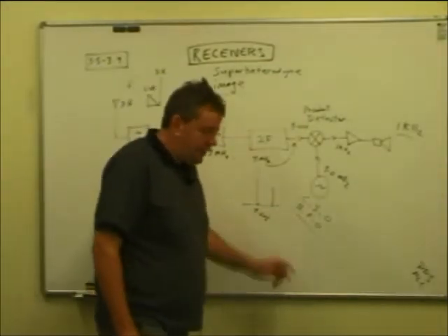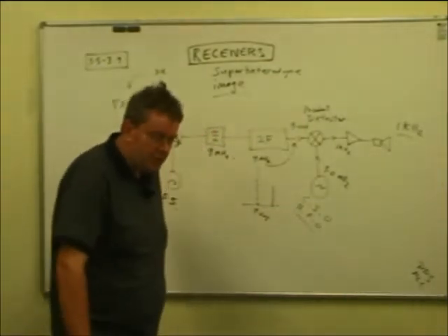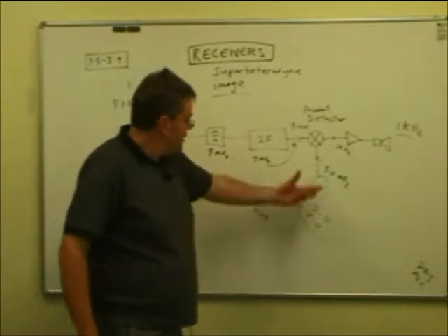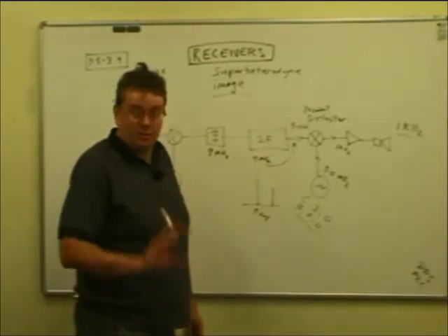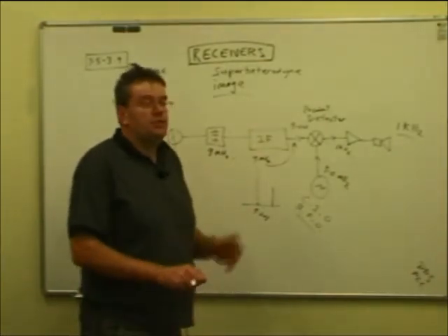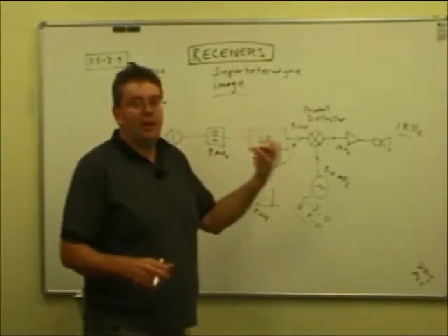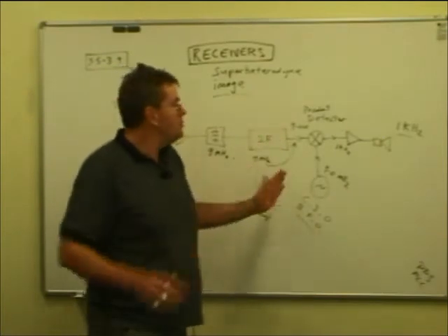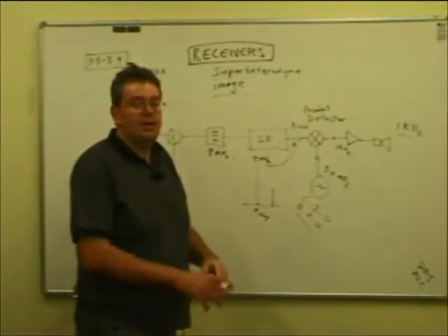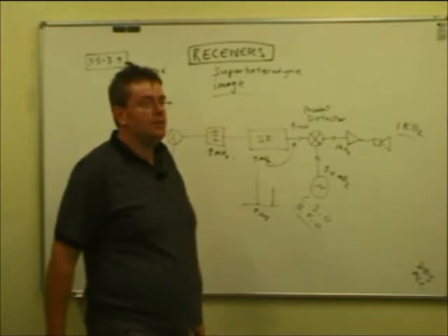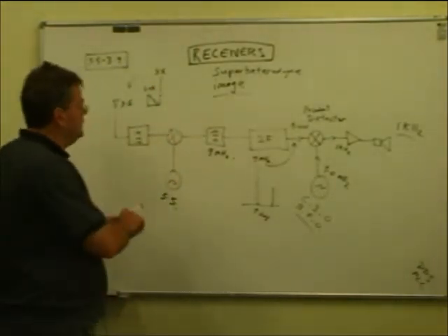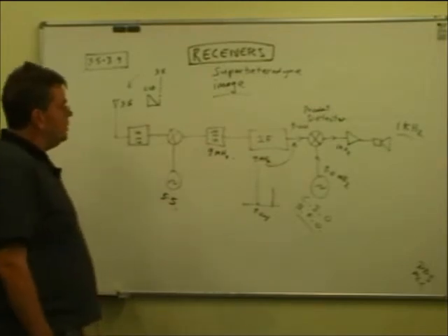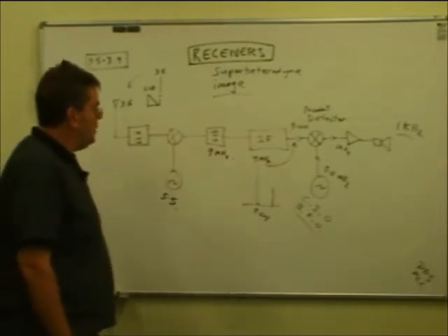And that's what old AM receivers used to have. You used to switch on a beat frequency oscillator, which was often injected into just the straight AM detector, and it still worked fine. Then instead of just hearing the carrier wave switching on and off, the two combined to produce an audio tone, and you hear the dee dee dee dee dee dee dee, you know, for CQ, if it was Morse code. Right. So that's single sideband or SSB receivers.